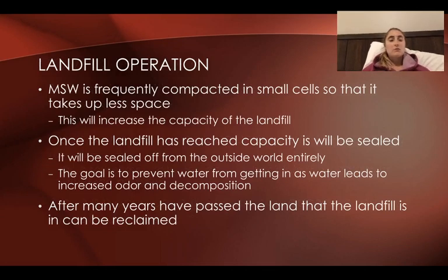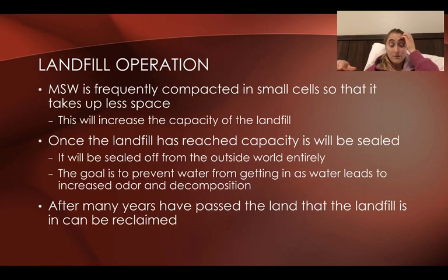Okay, so landfill operation. Basically, once the municipal solid waste gets there, once the trash truck comes and drops it off, they compact it. They compact it as small as they can into these small cells so it takes up less space. This will basically increase the capacity of the landfill. If they put everything in as is, it wouldn't be packed very nicely, and you wouldn't get as much in there. It's sort of like when you pack for a vacation, you put everything in really, really nicely when you first fly there, but then on your way back home, you shove it all in the suitcase and it barely fits, kind of like that.